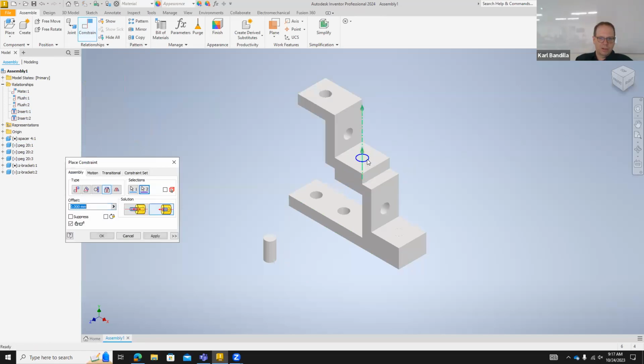This one. This one. Apply. And then we can do a flush. What that means is now instead of 4 constraints, we have 3 constraints. It's not a huge difference, but it decreases the amount of constraints we have, and it is the more natural one, you could say. The one that makes more sense.